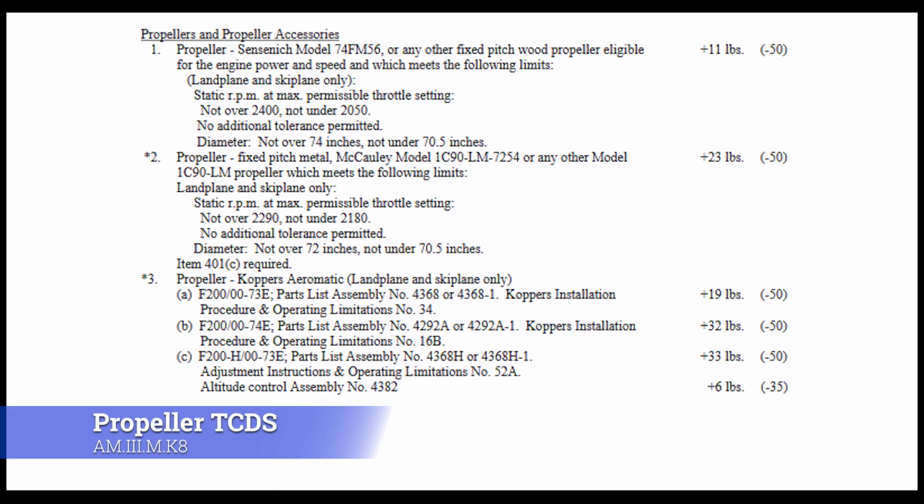The Cherokee actually has several that you can do, because this is just like the first three on a fairly decently long list. But there's a lot of them where you can only have one of two props, and that's all. And so that's something to think about whenever you're doing annuals, pre-buys, that sort of thing. Is that hey, look, is this prop authorized for this plane?